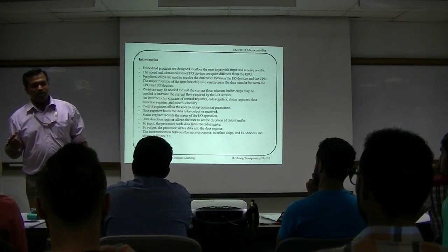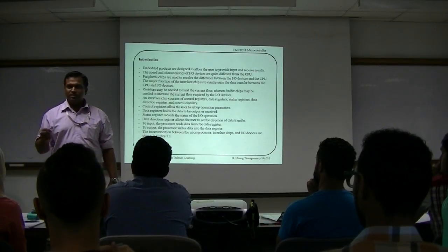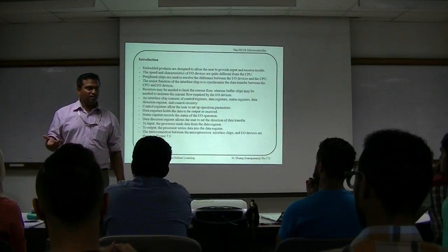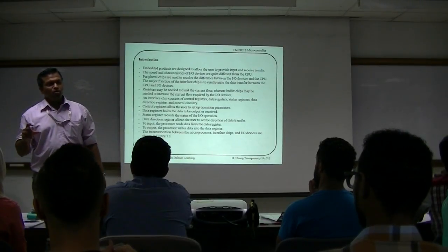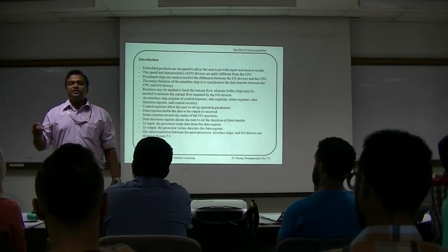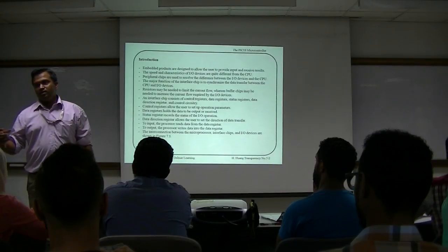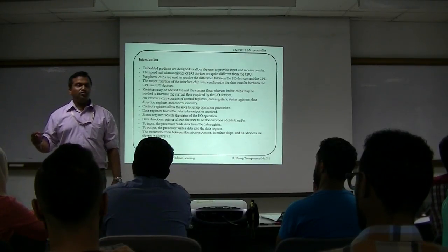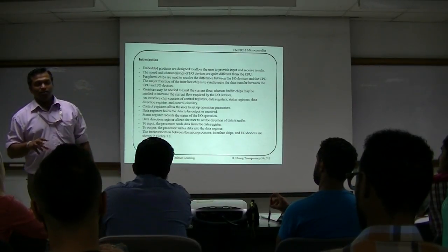We have learned about buffer chips like 7404, I can't remember the series, but you have to use this chip in digital lab, right? 74 series. So those are actually buffer ICs. That means they are actually used to increase the current, so you can drive 7 segments or motors which require higher current, which the microcontroller cannot supply.